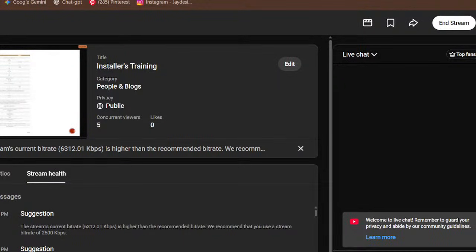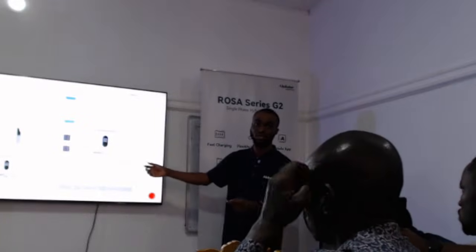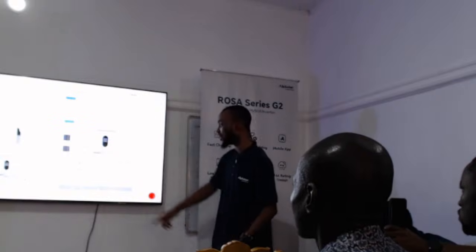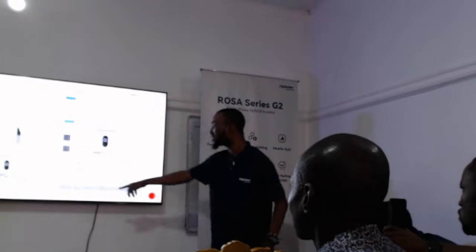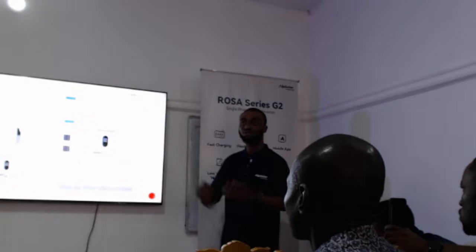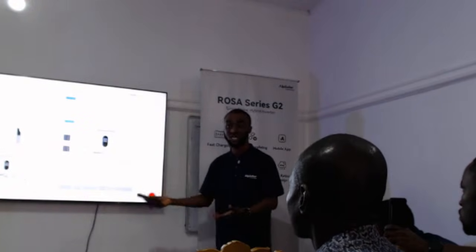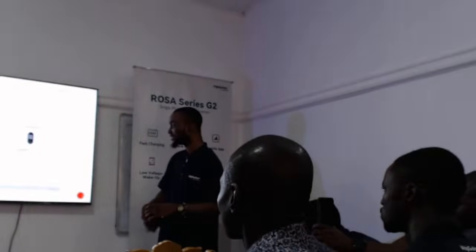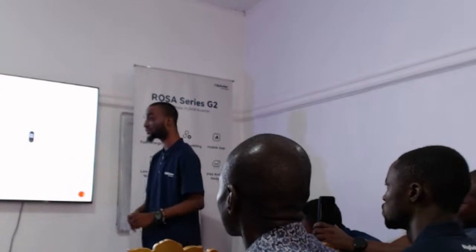These are the recommended breakers for our 11 kilowatt inverter. Don't forget that we used our 11 kilowatt as a case study. For our 11 kilowatt inverter, the battery breaker should be 63 VDC. The normal voltage for the battery is 51.2, so let's give an allowance of 63. It should be 63 volts and 300 amps. Most installers who have gone to sites for a 6 kilowatt inverter, I'm saying a 125 amps breaker is not ideal. If you cannot get a 300 amps breaker, you can get a 250 amps breaker.